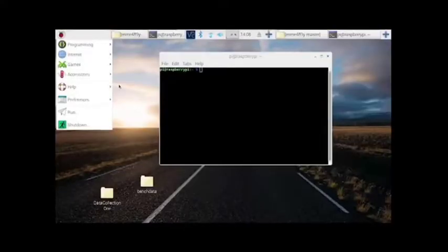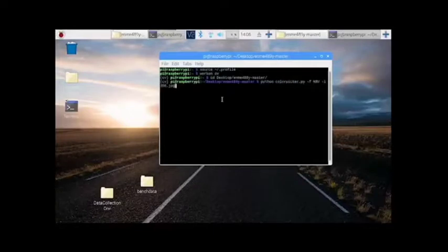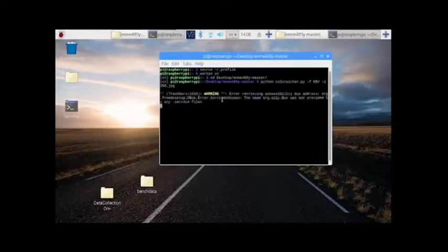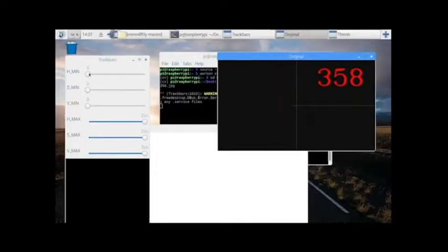An HSV mask or threshold was made for each side and section of scans. The HSV filter was applied in order to isolate the laser from ambient light. Then, using Python code, I applied the HSV upper and lower bounds and went through each row of pixels in each photo in order to pick out the shape of the laser light. Then, the distance to the target was found using the calibrated range curve. These values, along with angle measurements, gave the XYZ coordinates of the target.